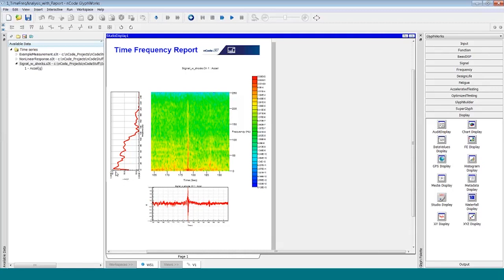You wouldn't be able to tell it's due to only one tiny little shock that occurs at a very precise instant in time. Or looking at the time series, you wouldn't know whether this excites a lot of frequencies or not necessarily. And it's interesting to see this plot because you know where your energy comes from, and you can tell, well, if there is a resonance somewhere around 100 hertz, this shock may excite it.